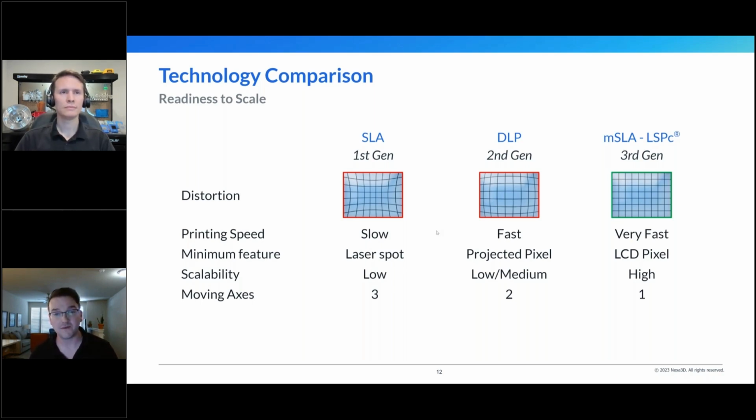And so in order to overcome that aspect, you've got to do one of two things. One is you move that projector a little bit closer and you shorten your build volume to just that solid, really crisp, clean projection point. Or you move that projector away, you leverage a little bit of that diffusion, but gain build volume. And we see both cases in the industry today.